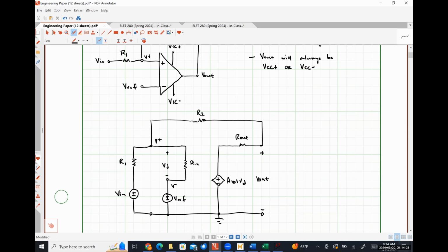So we are going to assume that the resistance Rn of the op-amp itself is much, much greater than the resistances R1 and R2, meaning that we're expecting R1 and R2 to be roughly kilo ohm size resistances and Rn to be roughly mega ohm size resistance, which is how we would normally bias an op amp for an input resistance that's on the order of mega ohms.